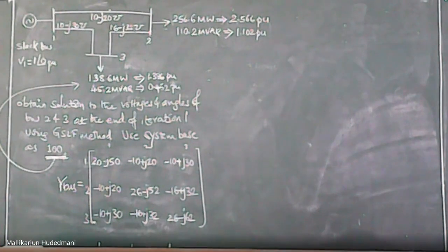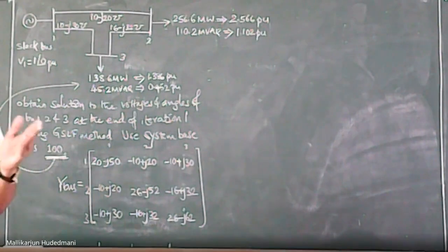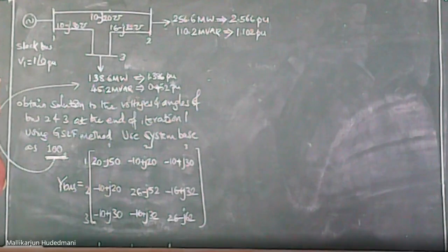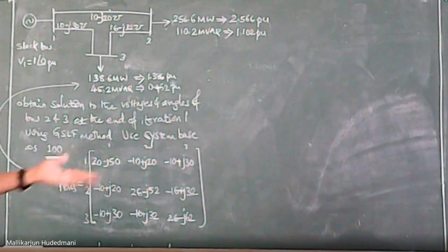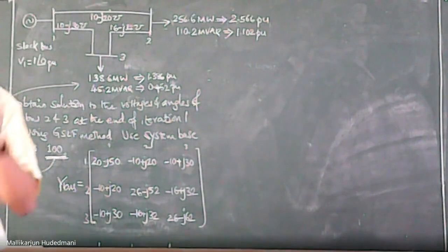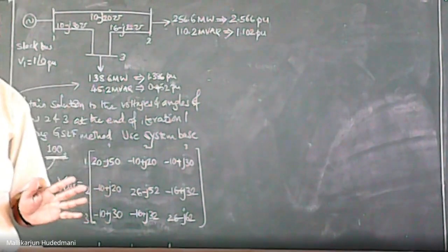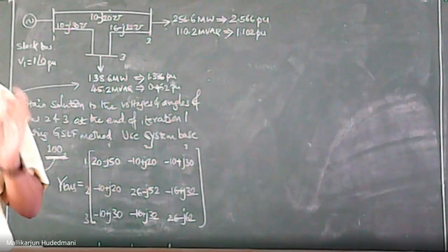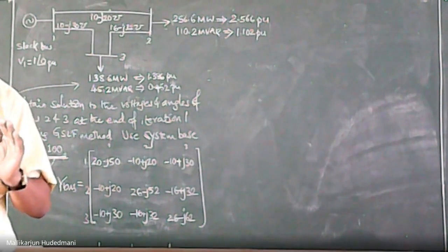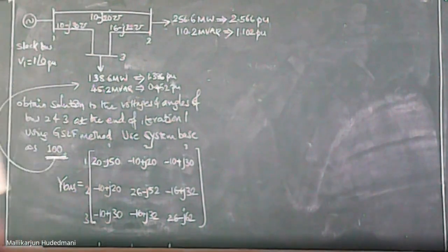This is the foundation, because if I go wrong here, imagine what is the V2 of 1? 1 by Y22, and inside the bracket you use Y21, Y23, Y24. Where do you use it? From the Y bus only. If this goes wrong, I am 100% sure your problem will be wrong. So seriousness must be there when you form the mathematical formulation of Y bus. If it is correct, your errors are reduced. So consistently, you will reach the destination step by step.